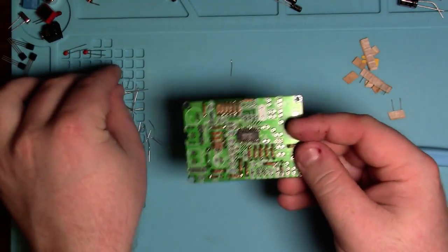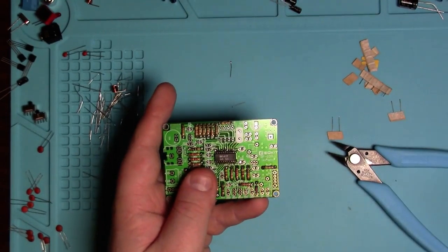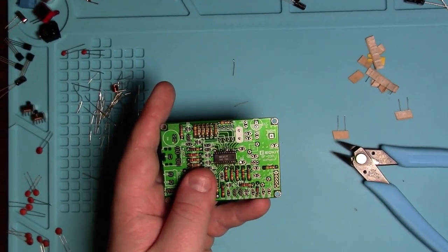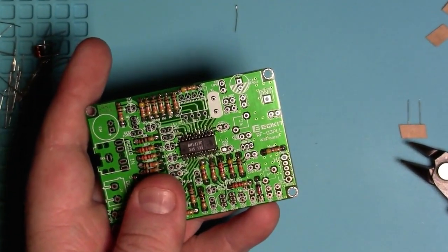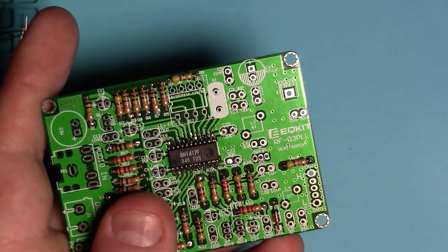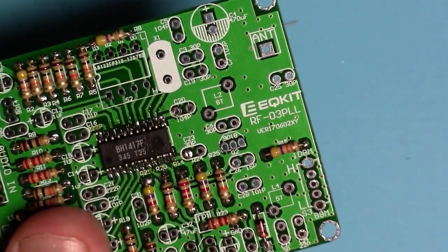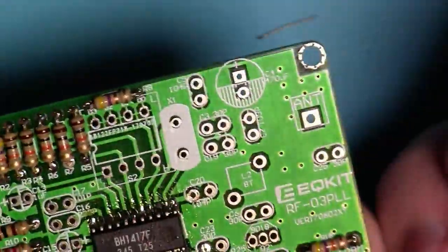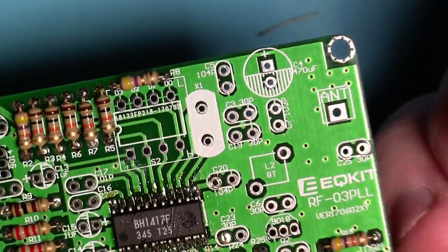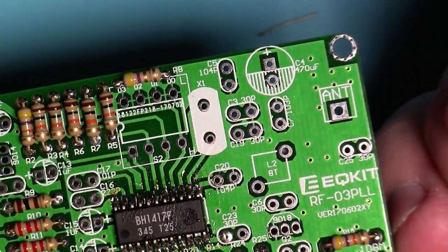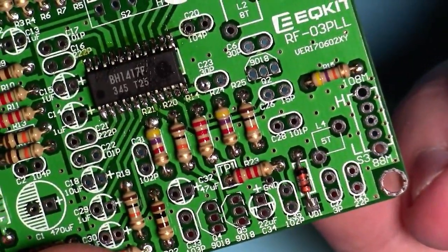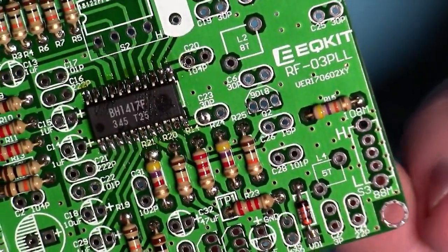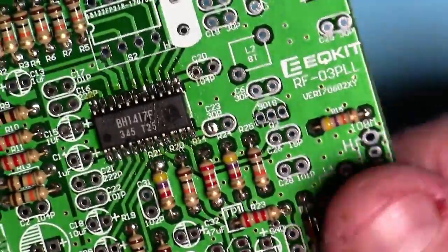Okay. So now while these are marked, so these are inductors. They're just a different type of inductor from the 150 microhenry one. Because these are just big turns of wire, it doesn't even register as a picohenry. So instead, they're marked with these boxes here, and you see where it says L2 8T, and it says L4 5T. So that just means it's 5 turns and 8 turns.